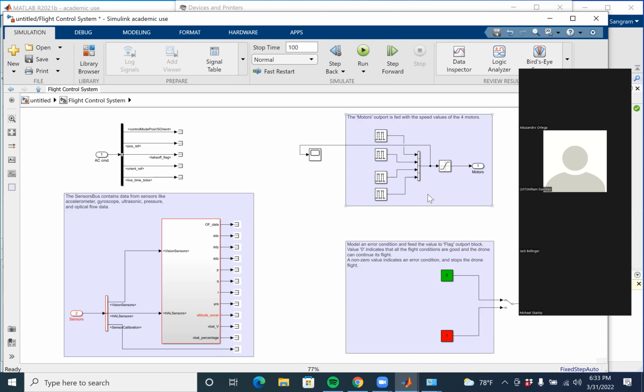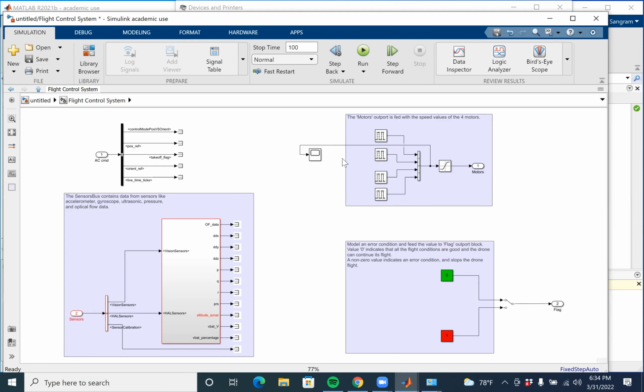For example, somehow your controller algorithm becomes unstable and it generates a PWM that is beyond the capability of the hardware. In that case, you have the saturation block that limits that PWM. So you would see saturation blocks almost everywhere when you deal with practical systems. But what I want you to do here is quickly attach this scope here.